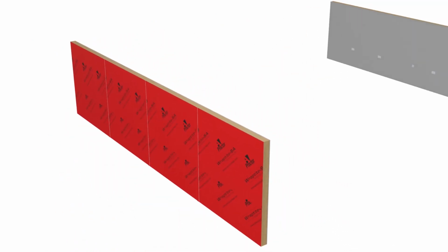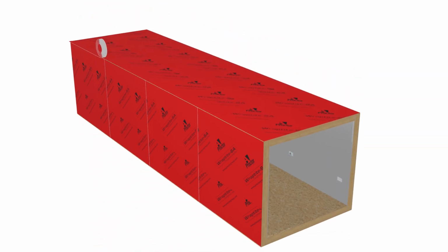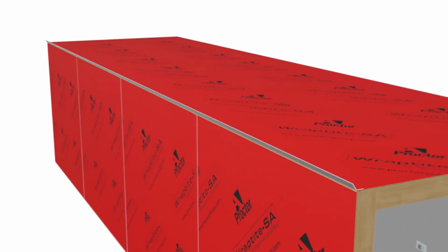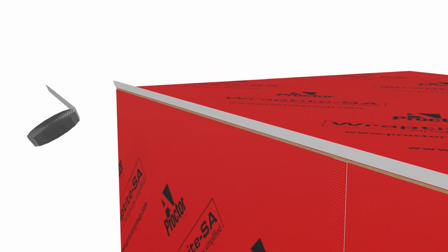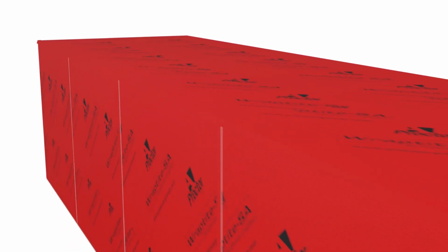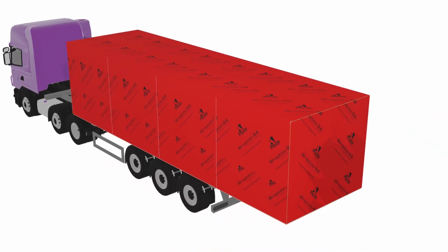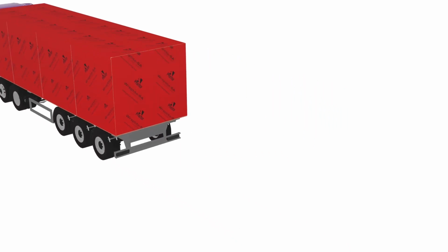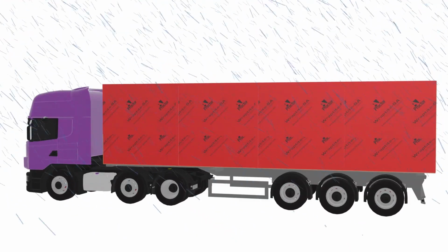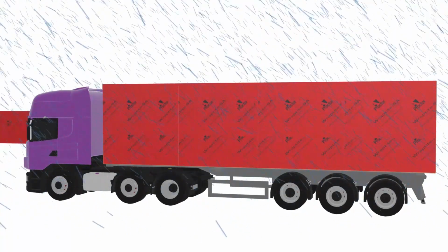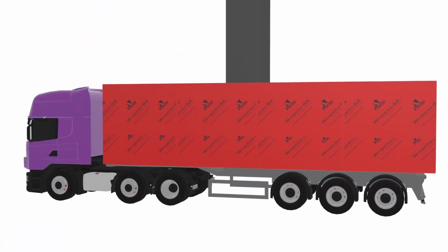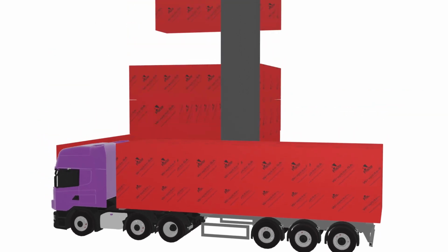These wall, roof and floor panels can then be assembled into modules, and the Wraptite split liner tape used to complete the airtight seal between adjacent assemblies. This tape simplifies making such joints by splitting the release liner in half, allowing the two surfaces to be stuck independently, making the joint faster and more accurate. The completed modules can then be transported to site. During transportation, the self-adhered membrane ensures watertightness, protecting internal components and minimising on-site remediation work. The building can then be assembled on site and completed as normal.